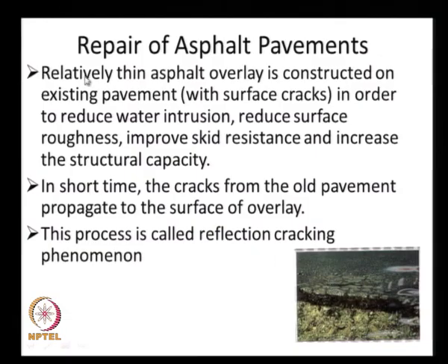So we provide a relatively thin asphalt overlay on the existing pavements that may have some surface cracks in order to reduce the water intrusion into the pavement, reduce the surface roughness, improve skid resistance and increase the structural capacity, because this is frequently done as part of the maintenance.